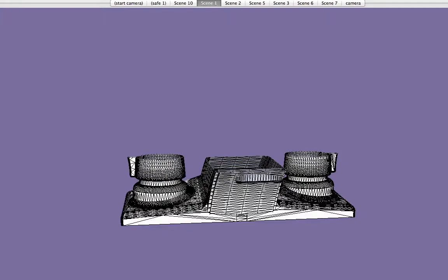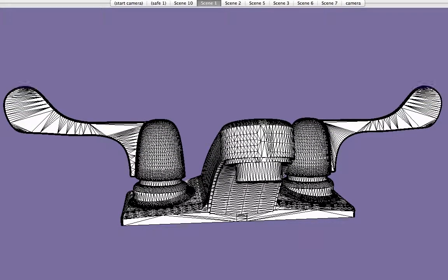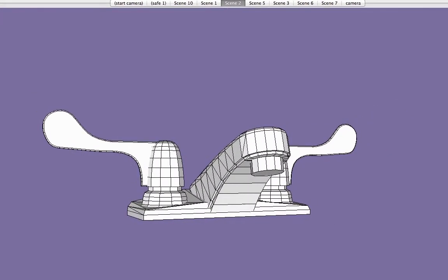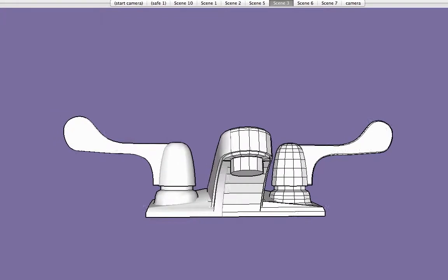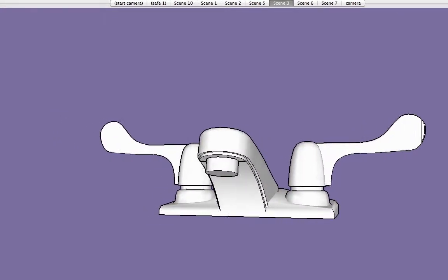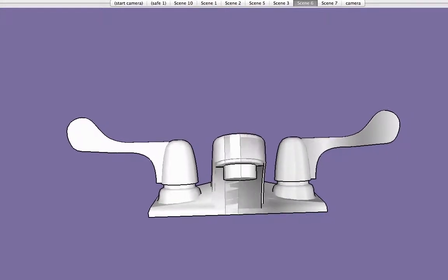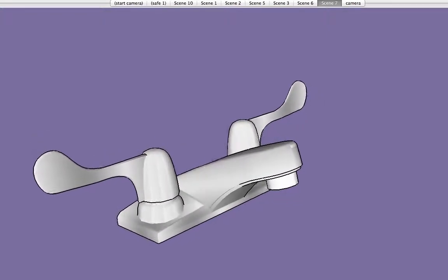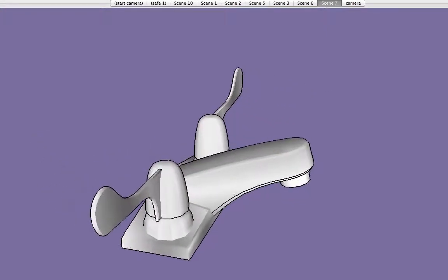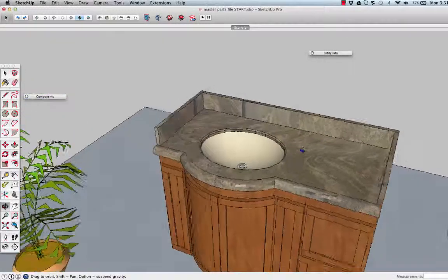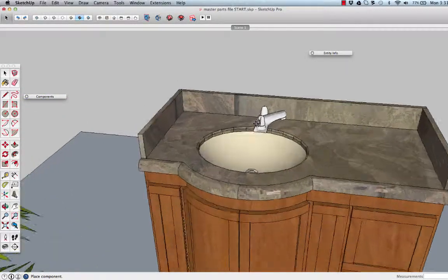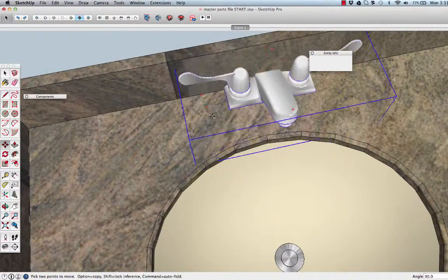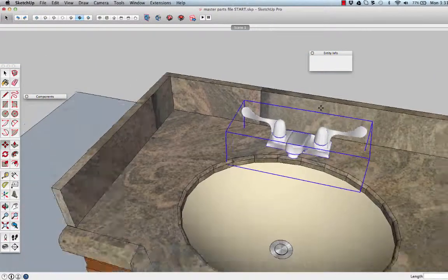Many engineering CAD programs are used to fabricate the actual building product. These files have far too many polygons for a design file. In general, you should model for visualization, design, or specifying, not for manufacturing. A great SketchUp product model is one that performs well in the context of a larger model, say a building, a park, or a floor plan, not as a standalone model. A component should represent a product's physical dimensions, giving the object a recognizable appearance, and enable the object to be positioned in the same manner as the product itself, nothing more.